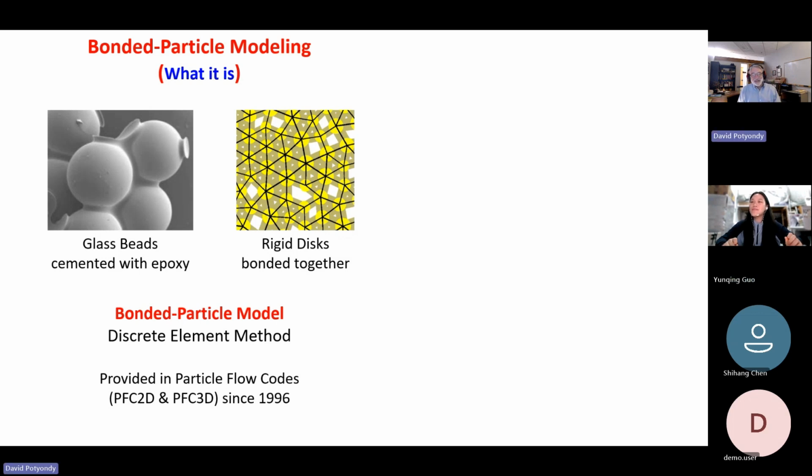And then what they do is they just slowly take out the broken material, and as they do, it provides less support to the roof, and then it collapses a little more. And so when you do this, if it works, you can literally remove like 3 kilometers depth of material, and there's nothing left. Eventually, the broken stuff goes all the way to the surface. They call this block caving. You're making the material cave in.